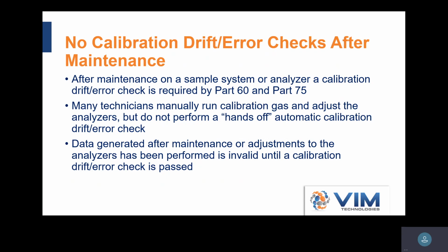So it's important that not only you do the calibration drift checks after, but that your technicians know why. Because every morning when you're doing the calibration drift check, the system's functioning in a certain fashion. But if I go in and replace a sample pump and replace a filter, maybe the vacuum's lower and the flow is higher.